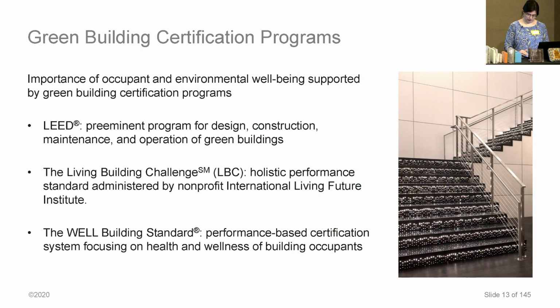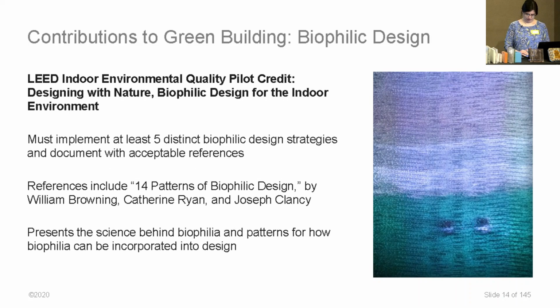The importance of design that benefits occupants and is sustainable, of course, is promoted by different building certification programs. LEED, WELL, those are probably the two biggest. So we'll be talking about some credits with those. And there's others, of course. Speaking of LEED, though, there are credits for biophilic design. So the idea behind getting these kind of credits is that you have to use a certain amount of biophilic design strategies. So we'll go through different types of these strategies and how they can be incorporated into the materials.